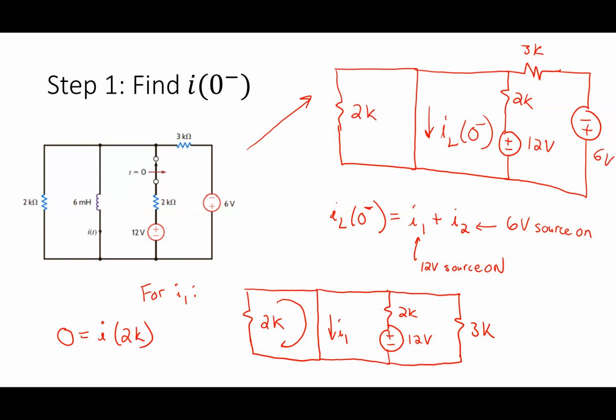All right. So I don't remember things like, well, a short in parallel with a resistor means no current. What's everybody say? Current likes the path of least resistance or whatever, right? Yes, it does. But why? Because KVL says so. All right. So the same is true with the 3K, right? Because I could do a KVL loop that included this short and this 3K. There better be no current through that guy either.